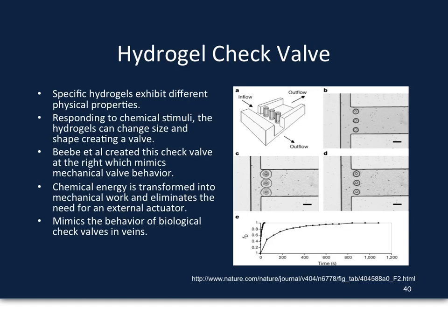So the whole idea of this particular embodiment is that you'd have these hydrogel posts here. And if you had fluid running by here and you added some chemical trigger to that fluid, then it would cause the hydrogels to expand and choke off the flow through this outflow channel. Whereas if you remove that chemical stimulus, then they'll open up and you'll get fluid flowing again.